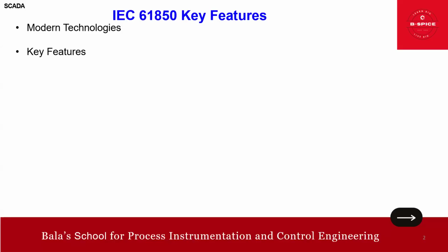One of the features is the use of a virtualized model. The virtualized model of logical devices and logical nodes enables the definition of the data, services, and behavior of devices, in addition to the protocols that are used to define how the data is transmitted over the network. So basically all the devices are virtually modeled here in IEC 61850.